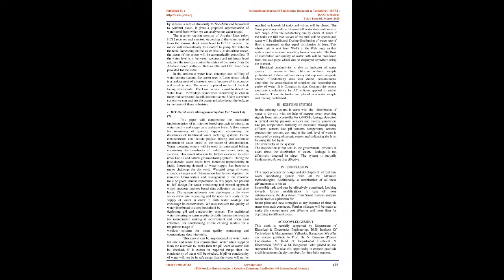It is placed above the tank and continuously monitors the water level in real time. This information will be updated in the cloud and the user can analyze the amount of water. These sensor values are sent to the water pump via the HC12 transmitter to turn the pump on/off. The sensor values are also forwarded to Node MCU, which is used for the IoT purpose.